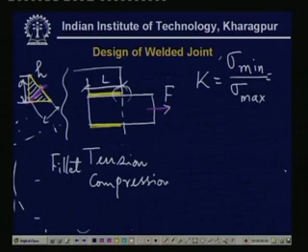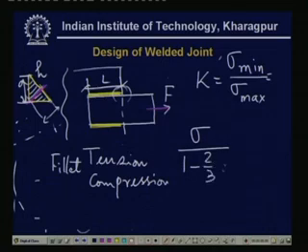They are given in the form of tables. Normally they look like some value sigma divided by 1 minus 2/3 k, where this factor is 2/3 now, and k is the same. So once you know this sigma for different types of loading, you may calculate the corresponding k, and then with this we calculate the allowable fatigue stress.